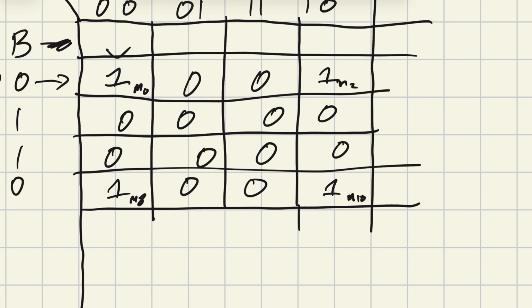As we previously saw, we want to group the ones in our K-map for sum of products as powers of 2. Well, over here, you may say that there's 4 ones, which is the power of 2. 2 to the power of 2 is 4, but we can't group them because they're not side by side to each other. Well, here's the beauty of a K-map. The idea of a K-map is you can group each of the ones around the K-map from both sides, up and down. So if we're going around the K-map, you can notice that this one is connected to this one if you had to turn the map over or roll it, if you could visualize that. And if you do that way, these two ones can be grouped together.